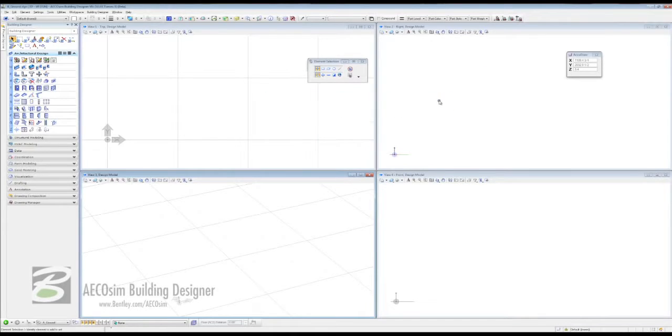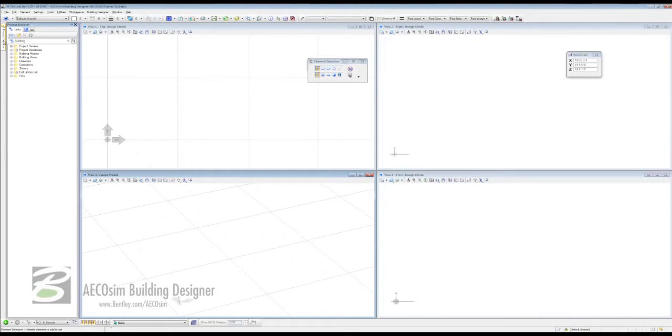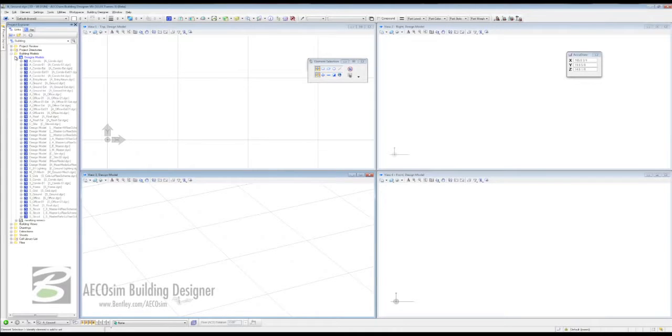We can just close down our models dialog box because now we're going to be bringing in the ground floor that's going to form part of the master model. The most efficient way of doing that is come across your task space interface all the way to the left hand side to Project Explorer. You need to twirl down Building Models and then your Design Models and come down to A_ground EXT because we have so far modeled the external fabric of our structure, and that's the one we're going to be putting together.